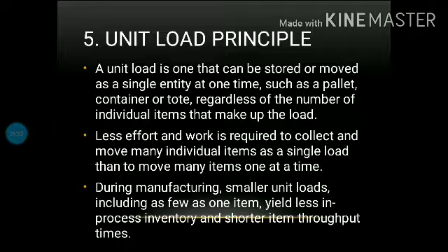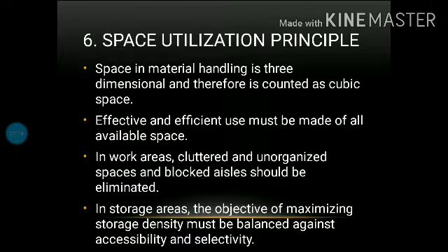Second one, less effort and work is required to collect and move many individual items as a single load than to move many items one at a time. Third one, during manufacturing, smaller unit loads, including as few as one item, yield less in-process inventory and shorter item throughput times. Sixth one, space utilization principle.